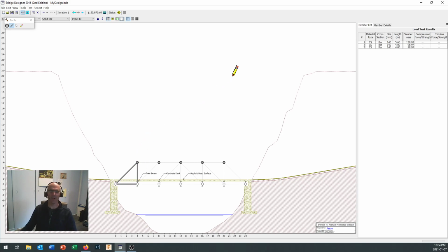By creating a triangle in your truss, you've pinned these three nodes together in such a way that they can't pivot, because for this to pivot about here, it would need to change the length of this member right here. So this member is locking this member in place so it doesn't rotate about that node. That really matters.